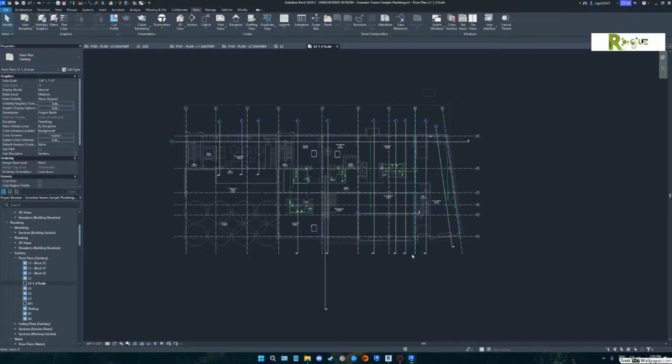Because remember, a lot of what we name in Revit will have to get pushed out to a loadable family. And if we've used that name in a loadable family, it can drive you nuts why you can't open the family. When you try to open and edit the family, you have all kinds of problems. Don't name with those bad characters. So if you can't name a file with it, don't name it. Okay? All right.